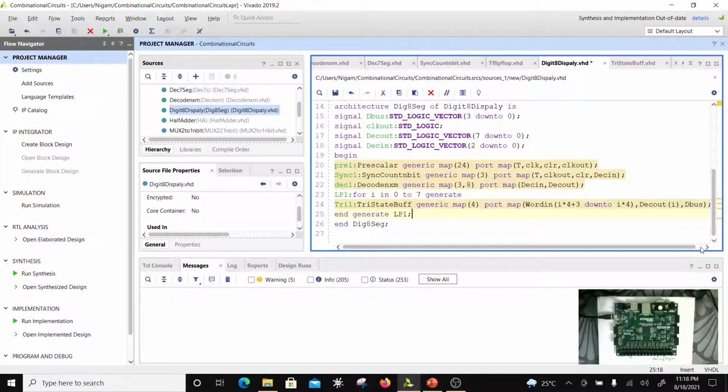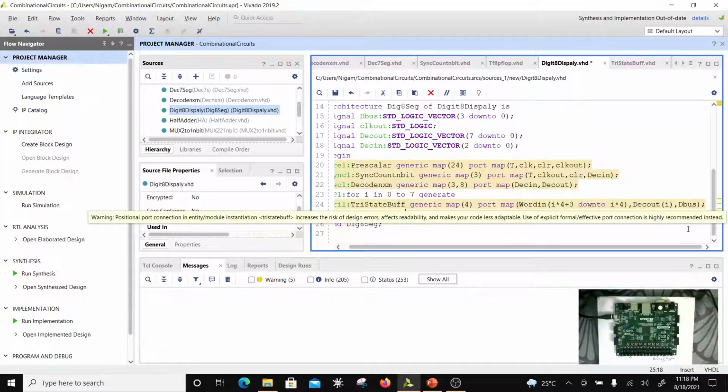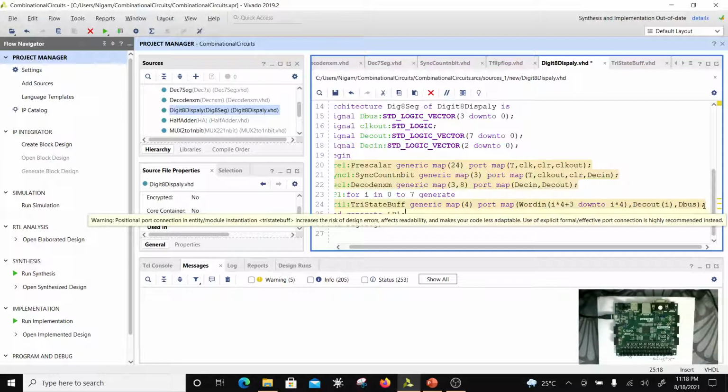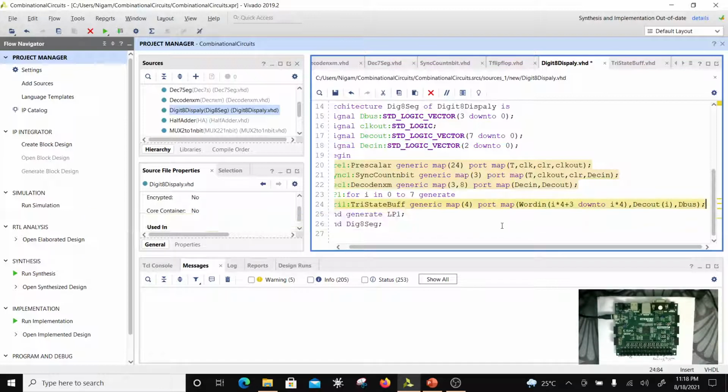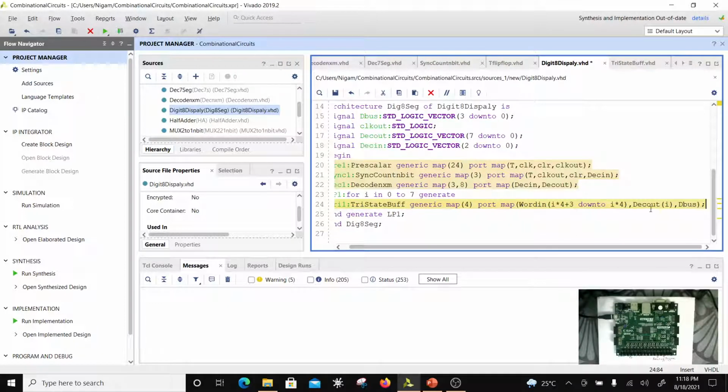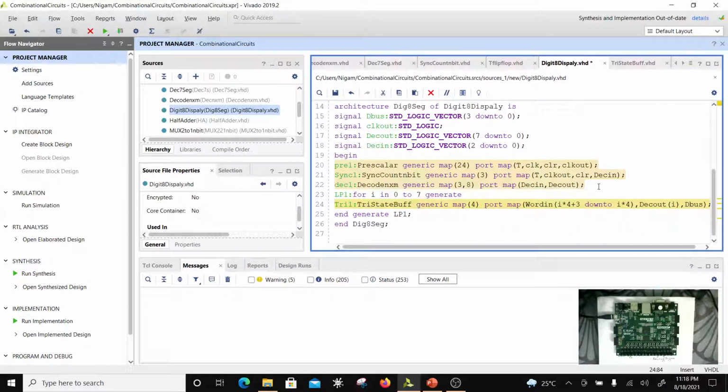And this is going to be having an output enable as DEC out 0, and this is putting this on a D bus. So at any point of time, that particular segment will receive the data on this D bus. Correct? Okay, so that will receive data on D bus, and it is going to be multiplexed by the decoder, whichever data is placed, and that decoder is also generating the controlled output, right?